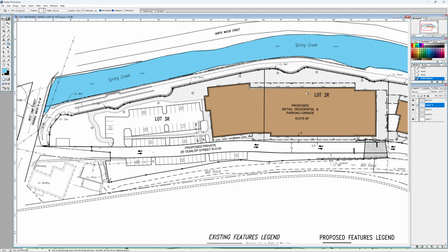Blocking out the colors, that's the first thing I always do. So let's say I do proposed paving and I'll pick a gray. I usually try to get somewhere around 25%. If you hover over, it's 30, so 25. I'll make sure all my layers are on. I'm on my own paving layer. I'll just click wherever I think there will be proposed pavement, and that gets it filled in pretty quickly.